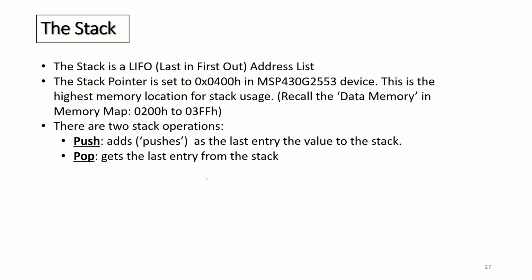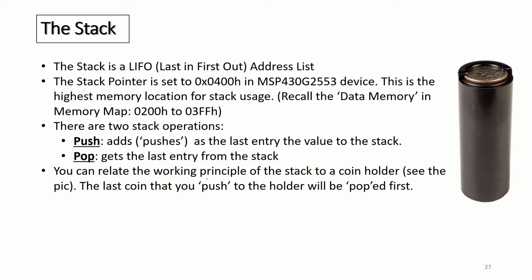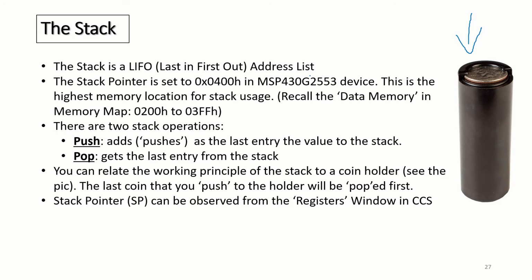Push adds or pushes as the last entry the value to the stack, and pop gets the last entry from the stack. You can relate the working principle of the stack to a coin holder. The last coin that you push into the coin holder will be popped first. Stack pointer can be observed from the registers window in CCS.